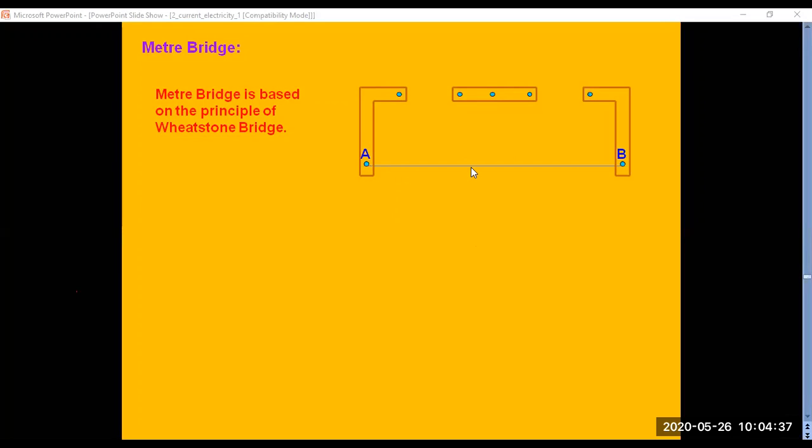What a meter bridge is, is depicted here. You have 2 L-shaped metallic plates denoted by A and B at both ends. Now you see the connections that are made. For these ends A and B, the green line you can see is connected to a battery and a plug key. The plug key is just there as protection for the circuit. If you put it inside, it will be closed. If you pull it outside, the plug key remains open. It's only for connection, so keep this clear.